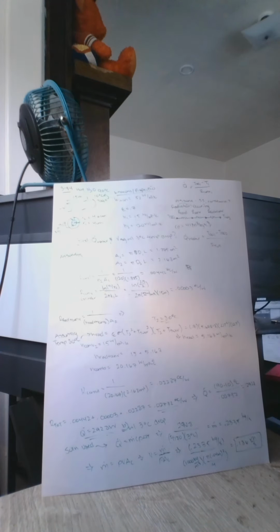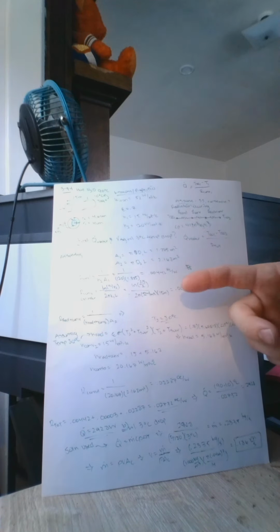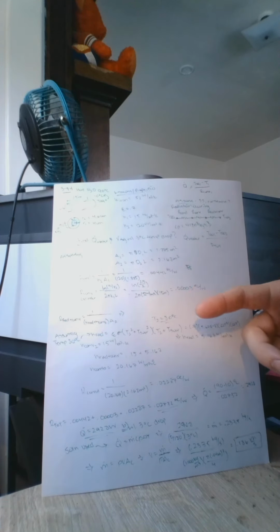In question 3-94, we had this long wire right here, and we were asked to find the heat transfer to the water as well as the velocity with a 3 degree temperature drop. First of all, to find the Q of the water, once again, we use the resistances found between the piece of pipe, which can be seen here, as well as the resistances over here. We calculated the resistances to get an R total.